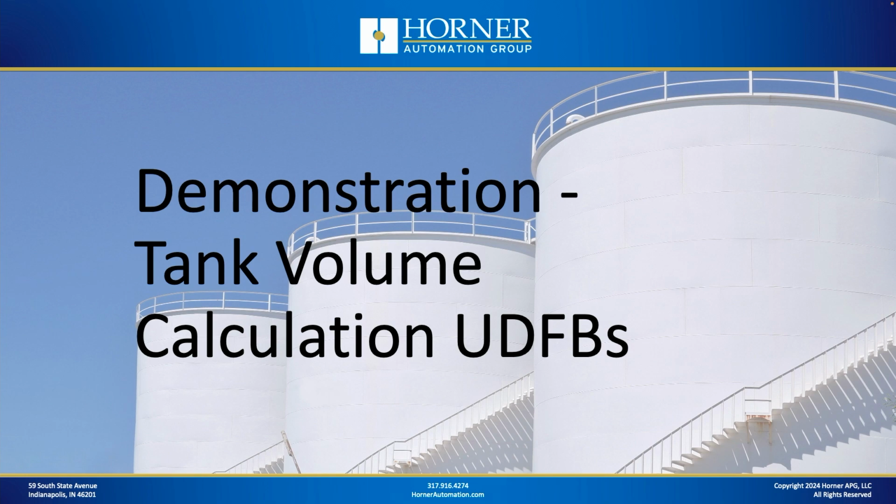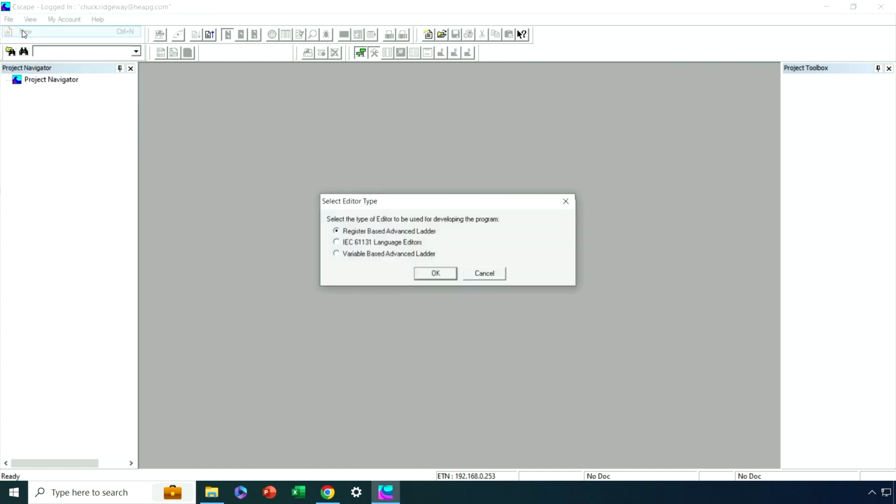Okay, without further ado, let's take a look at our demonstration. Let's see how we can use these user-defined function blocks that we've created for you. Okay, so I'm going to start with a fresh program. You don't have to do this, of course. You can import it into an existing program. The only requirement is that you have to be using variable-based advanced ladder or IEC. These specific UDFBs I've created are for variable-based advanced ladder. I could very easily create the same ones for IEC, but I haven't done that yet.